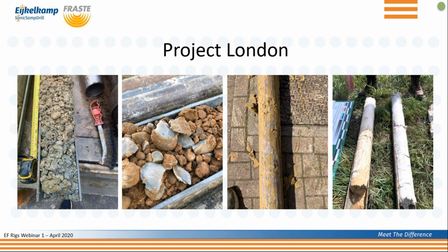Again, this is where the sonic comes into its own, and a cable percussive rig will hit the Lambeth clay, hit the sand lens or the sand bands or the black pebbles and say they can't get down or they need different casing, and quite often, more than not, the engineers will be left in a situation where they have to pull the borehole on a refusal, whereas the Sonic can just carry on as normal. And, you know, if you give the Sonic drillers a depth, they'll hit that depth. They'll give you 100% recovery, regardless whether it's London clay or Lambeth clay or Lambeth sands.